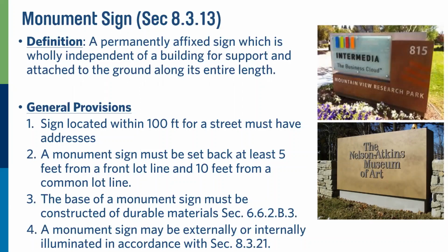You have to make sure, especially if EIFS, exterior insulation finish system, that is just styrofoam. All right, and it will soak up water, and there's lath on it, and it'll start rusting everything out. So that's why you have to keep any type of porous materials above ground, typically at least 8 inches. And these signs also can be lit up.